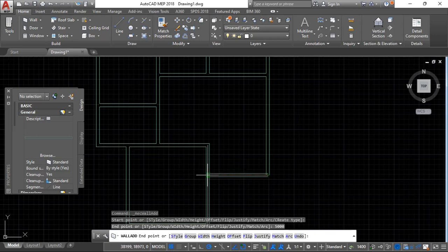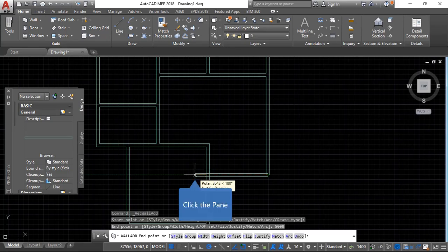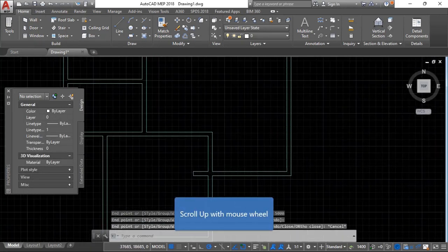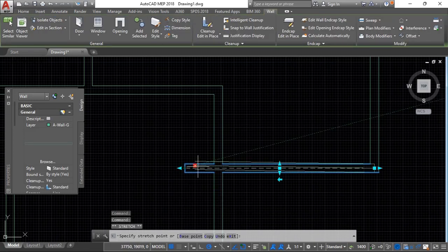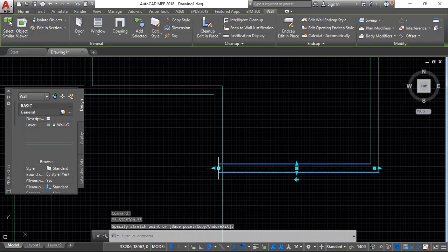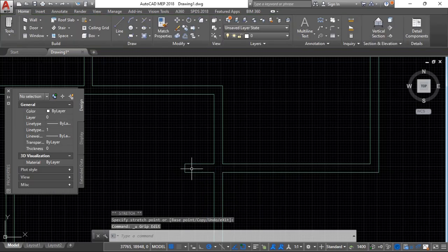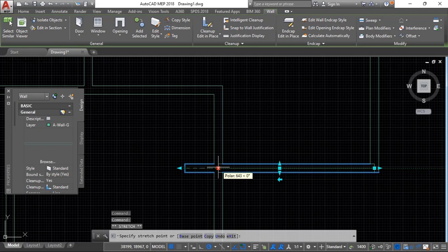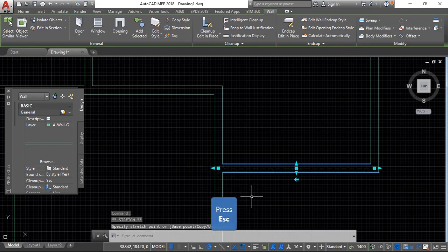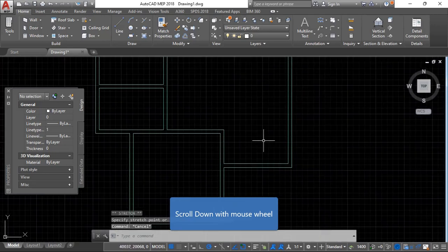And so like before, nearest could be disturbing at that point, so just make it go beyond and then pull the wall backwards. Just click there and pull it backwards to intersect. It has to intersect. Make sure it intersects with the midpoint there. Don't leave the wall hanging.